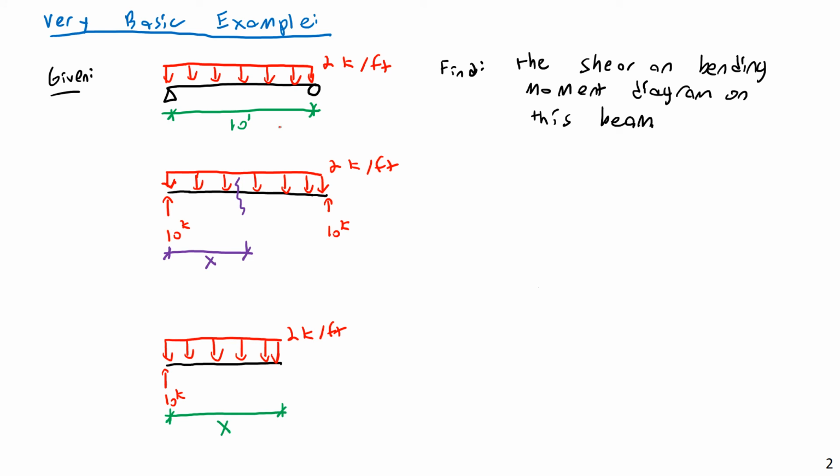Perpendicular loads contribute shear and moment, while loads parallel to the axis of the beam contribute to your axial force. Back to the shear and moment, we focus mostly on those because they're the real tricky ones and have really interesting integral relationships. Axial force is more just axial force. We'll learn later that there is an integral relationship between load and shear, and an integral relationship between shear and moment, and so that builds layer by layer. Axial force is simply the axial force present in the column. It's a little bit simpler.